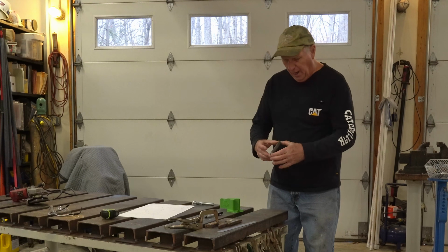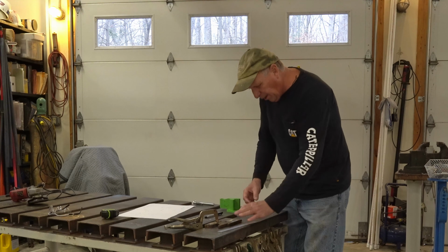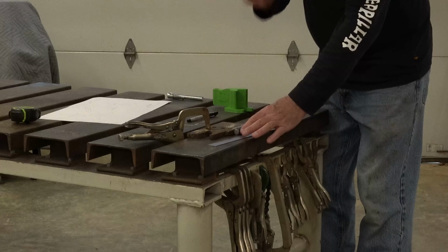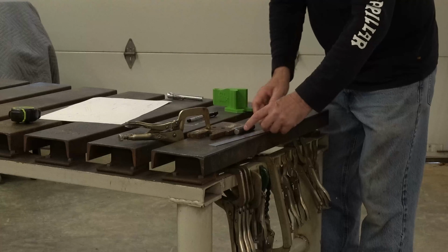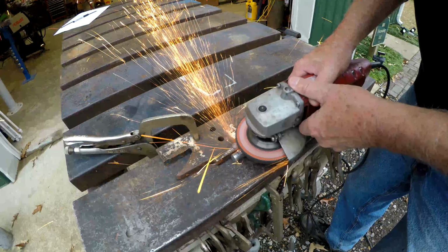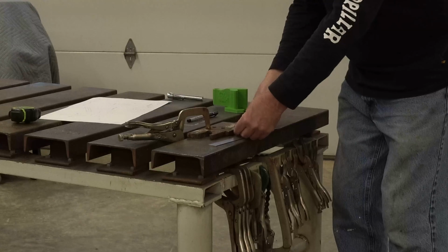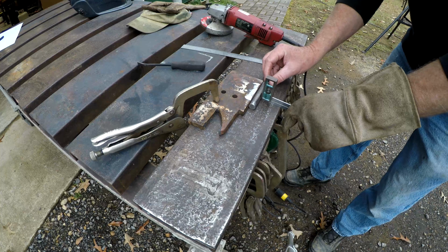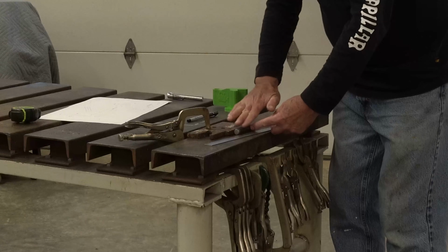To do this, I have a piece of 1/2 inch stock that I'm going to lay right beside this pin, and I'm going to put a tack weld on this back edge. Then I'll mark where I want the flats to be. I'll come in with a grinder and use this piece of 1/2 inch stock as a gauge for how deep to cut that flat. Once that flat is done, I'll break the weld, rotate it 90 degrees, mark it again where I want the flat to be, and grind that area down to 1/2 inch high.